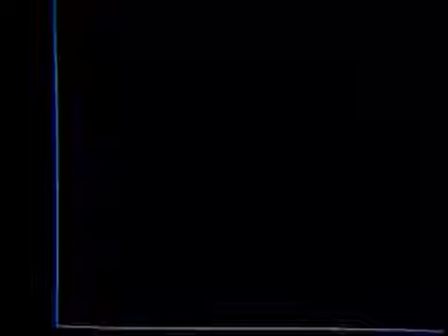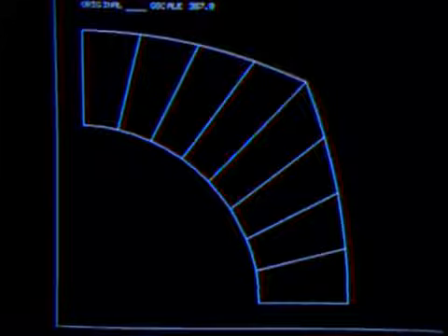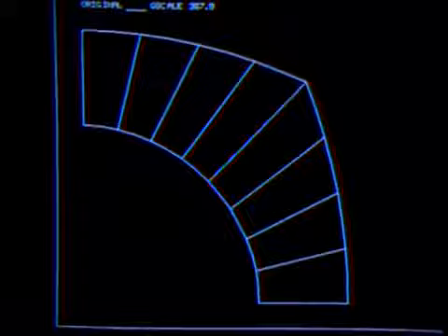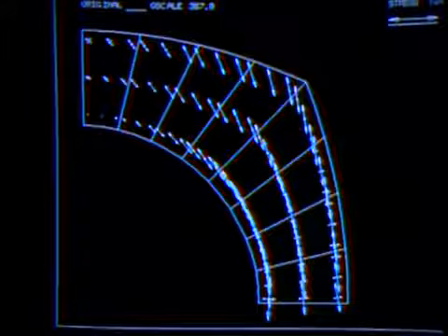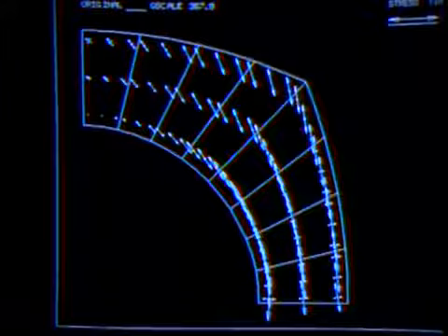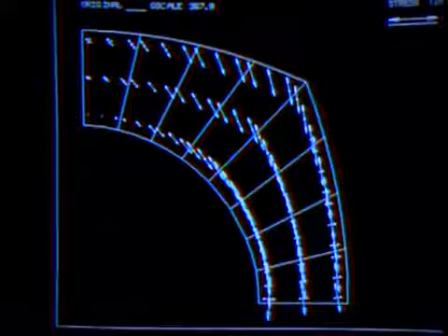However, note that the nodal points on the horizontal symmetry line have not displaced at all. This is quite unphysical and shows that the wrong boundary conditions have been used. If we look at the stress vector plot over the mesh, the same conclusion is reached. For clarity on the video, we show here the stress vectors just on the elements closest to the hole. And we can see in the element adjoining the horizontal symmetry line a stress that acts normal to the hole. This is, of course, unphysical.